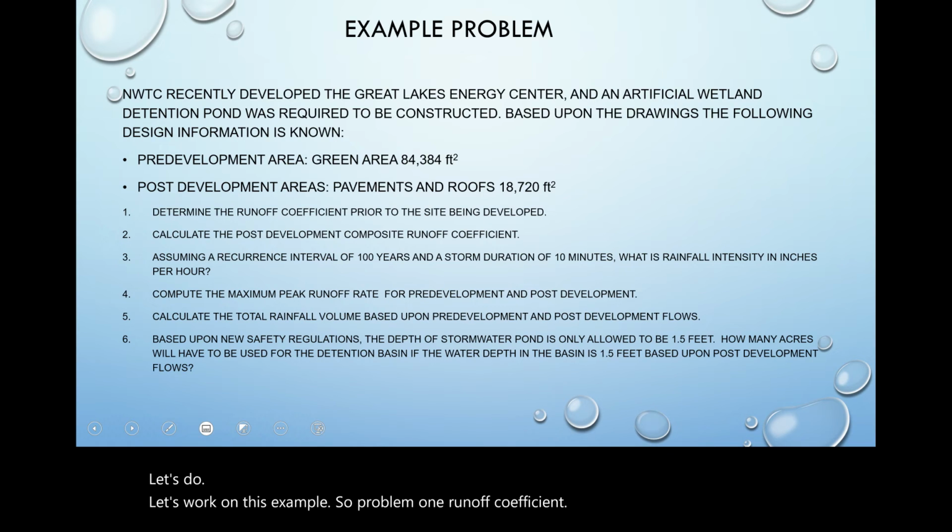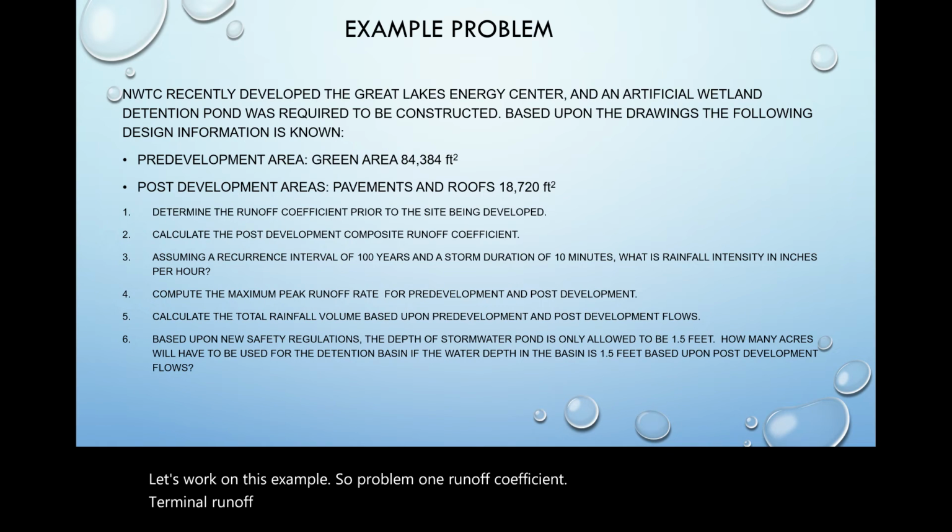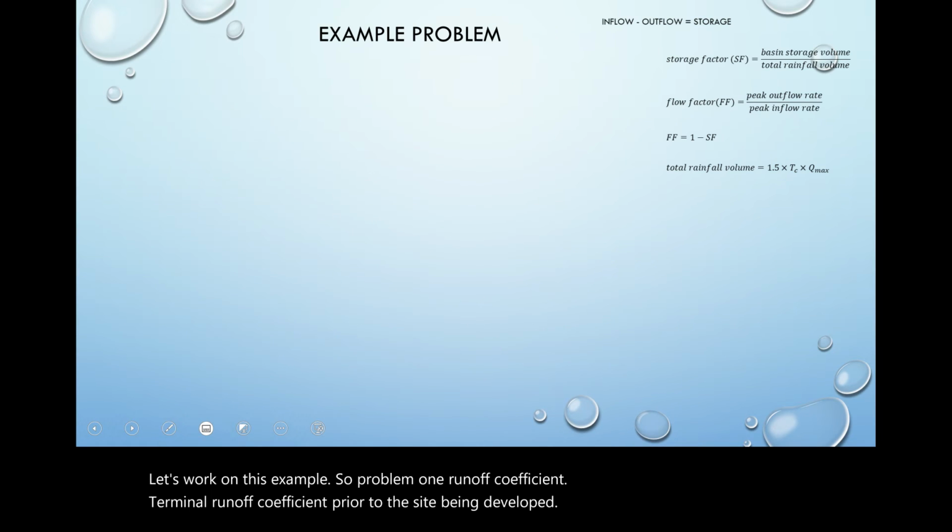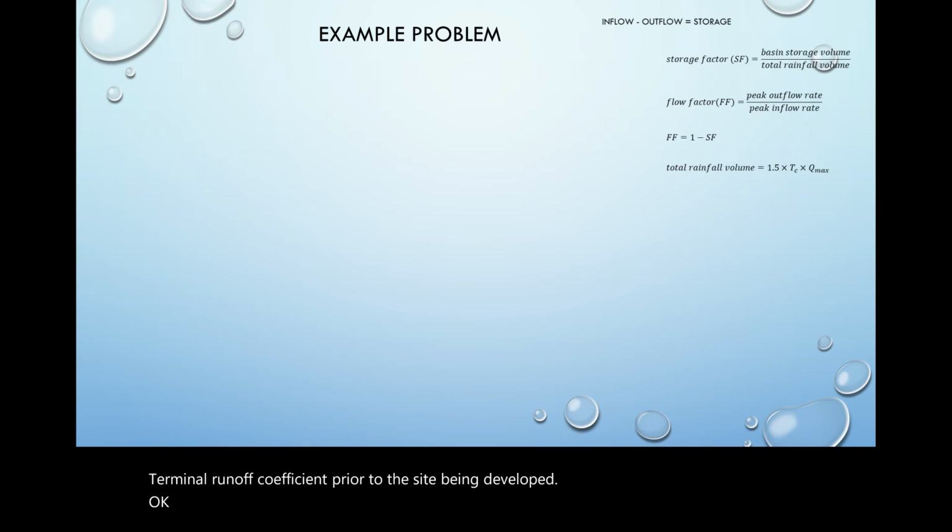So problem 1, runoff coefficient. Determine the runoff coefficient prior to the site being developed. Basically for number 1, I am using table 9.1 on page 219.